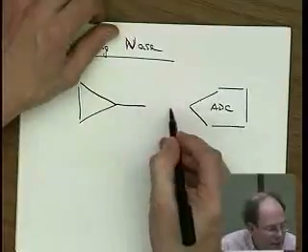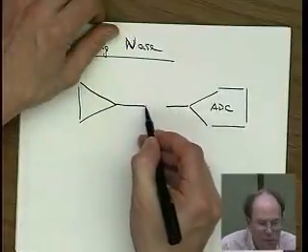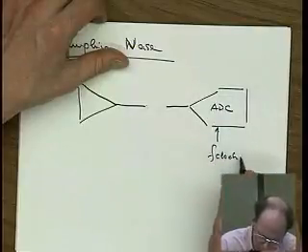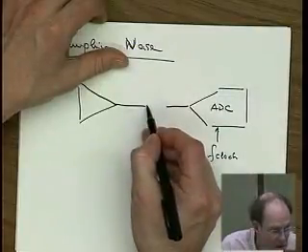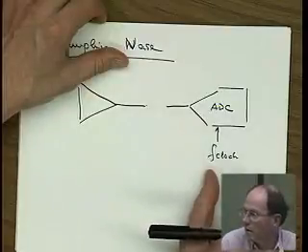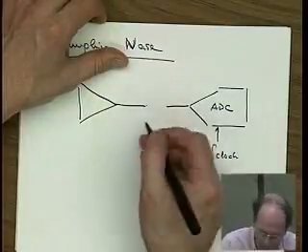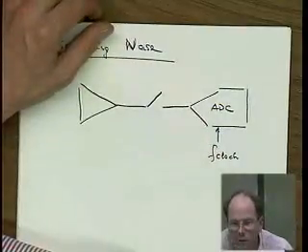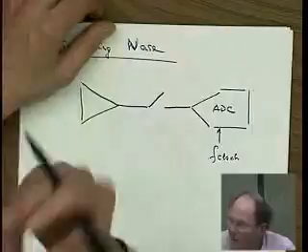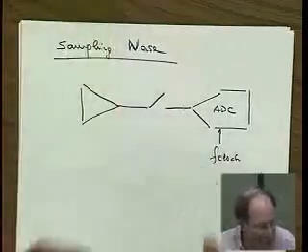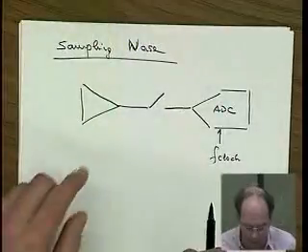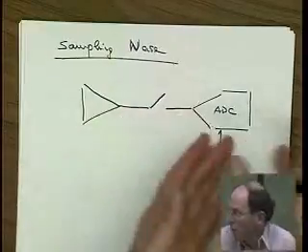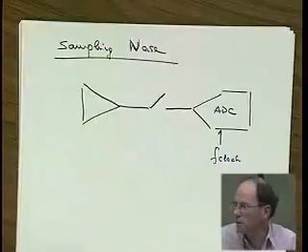Well, the ADC, in order to grab the signal, runs on a clock, right? And so with the frequency of that clock, let's say 1 megahertz, every microsecond it closes a switch, quickly looks at the signal, and at the end of the microsecond it opens the switch again, and then it has captured the value and it converts it. Now, if you had 1 volt here, then it would capture 1 volt there, and it would then convert that 1 volt and give a digital representation.